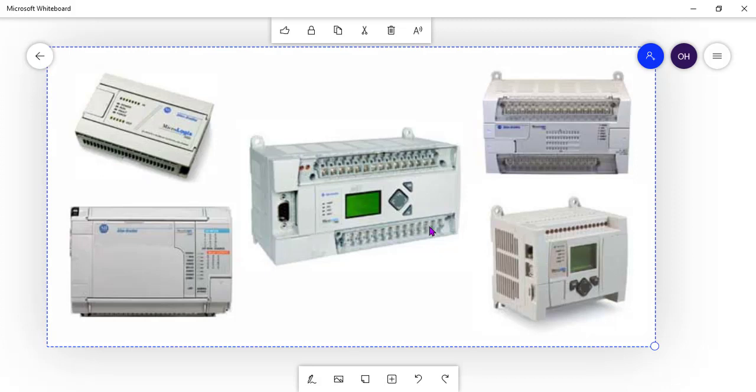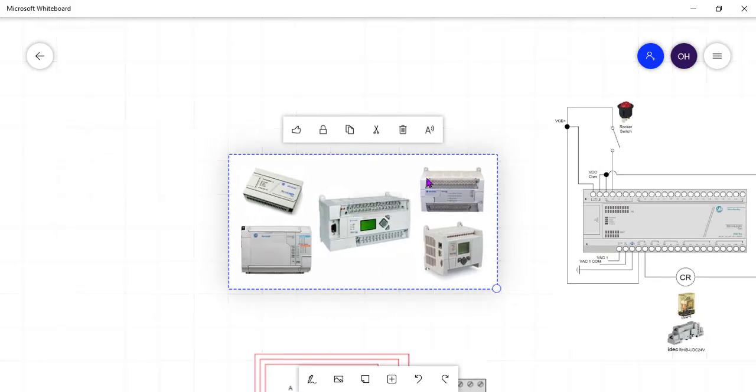So these are PLCs. All you do is to buy the PLC, make your connections, connect the input: your switches, your push buttons, your sensors, your flow sensors, temperature sensors, limit switches, contact switches. Then the output is from here. So the input is from here, the output is from here. But the output depends upon the nature of ladder logic written and downloaded into the PLC.